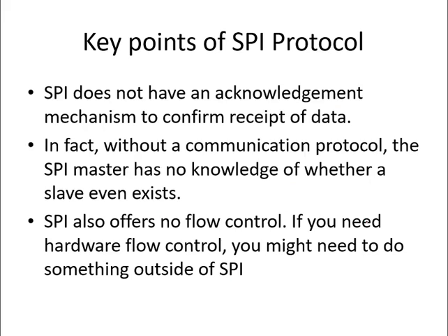SPI does not have an acknowledgement. Now, acknowledgement was present in case of the I2C protocol. It will always send one acknowledgement bit saying that it has received the data correctly. But in case of SPI, it does not have an acknowledgement. So there is no confirmation that the data is received properly. You have to just go on sending the data, either master will send the data or slave will send the data, but in either case the sender will not know that the receiver has received the data. So it is not that faithful a communication.